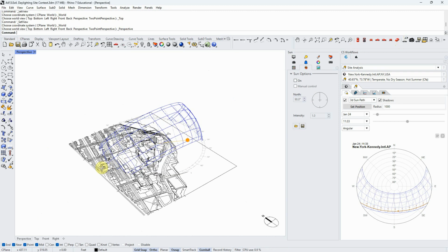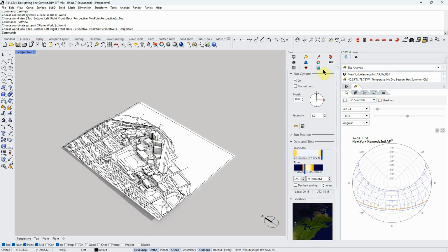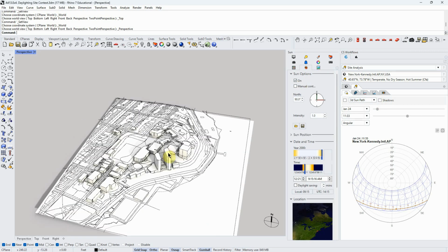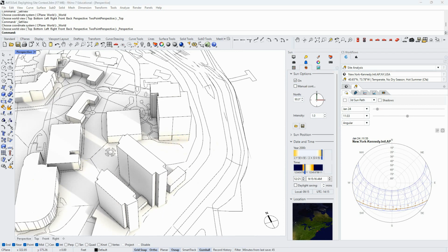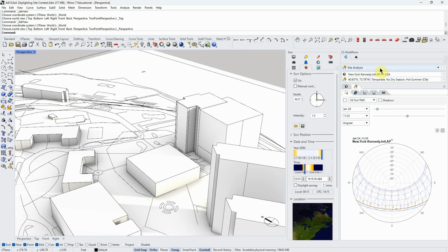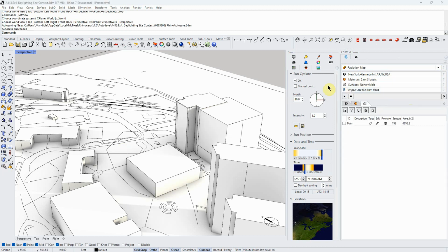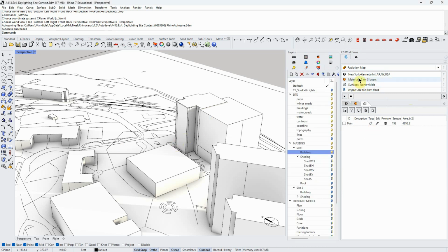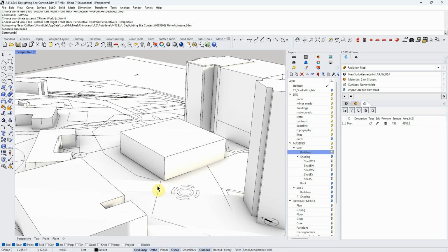Okay, so those are powerful visual tools, but we're not getting any quantities out. One of the main goals of this class is to quantify this stuff, and to design to benchmarks that are part of our program. The next level of daylighting analysis would be a radiation map. If we come back to our drop downs in Climate Studio and I choose radiation map, we see similar inputs to the daylight availability analysis that we did last week. That's a great thing about Climate Studio, that a lot of the inputs are the same.